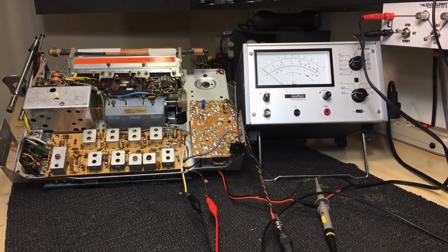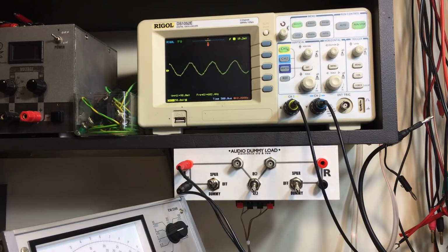So all is set, and I'm going to turn on the signal generator at 455 kilohertz with a 30% modulated 600 Hz tone. And it would help if I switched on the unit. And I can hear it. If I switch off the modulation, I just get hiss. Switch on the modulation and I can hear it. Not only can I hear it, but I can see it on the scope.